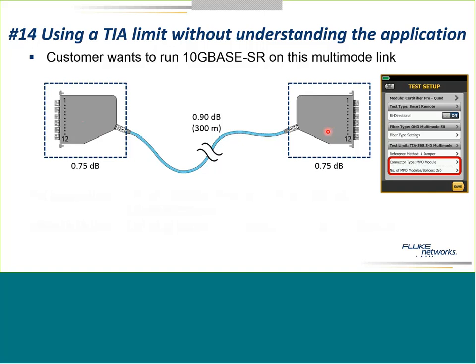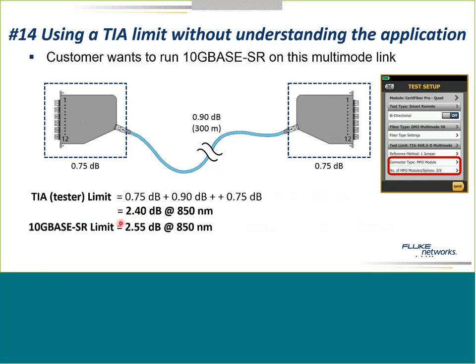Now, this is very important because we just saw that even in this case, we've got 0.75 in our 300 meters, gives us 2.4 dB of loss. We're getting to be right there for 10 gig. And if we had 2 sections of cable, obviously, it couldn't be 300 meters between each one, but if we've got two, say, 100-meter trunk cables and we've got 4 couplers there, got to be careful about what our loss value is.